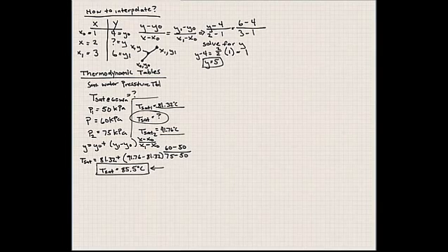Okay? It can't be above that, can't be below that, since we're assuming it's a positive linear slope between those values. So as we increase the pressure, the saturation temperature was also increasing. So it had to be between those two values. So if you did this calculation in class, a good check for you is to make sure that it's somewhere in between